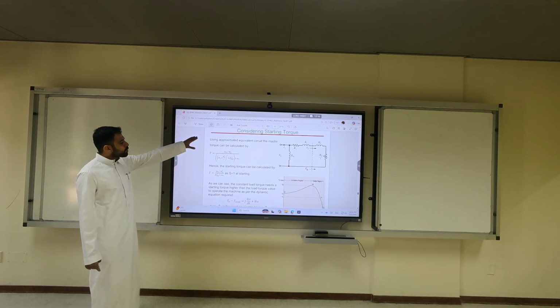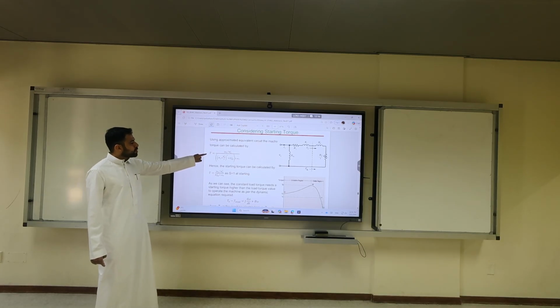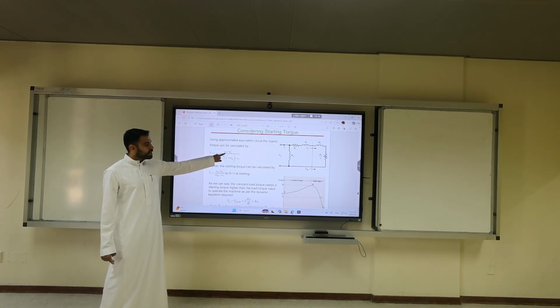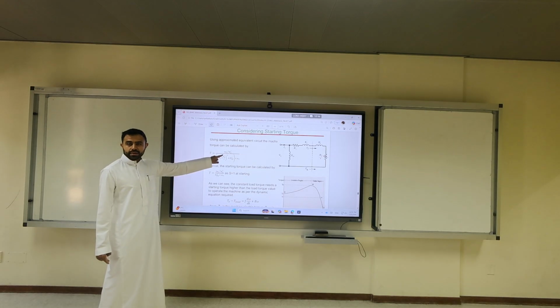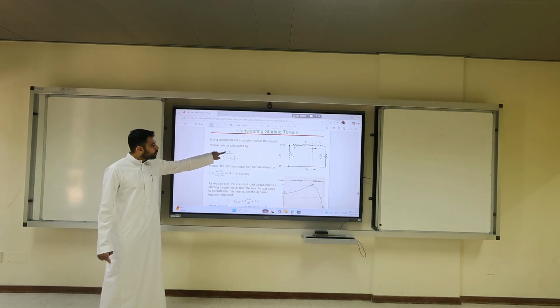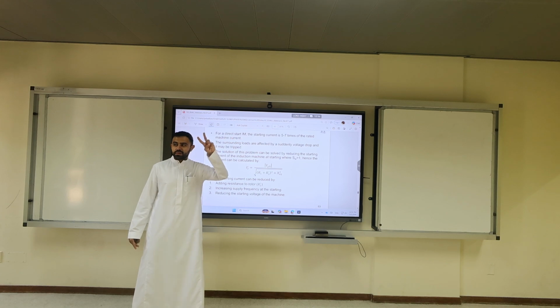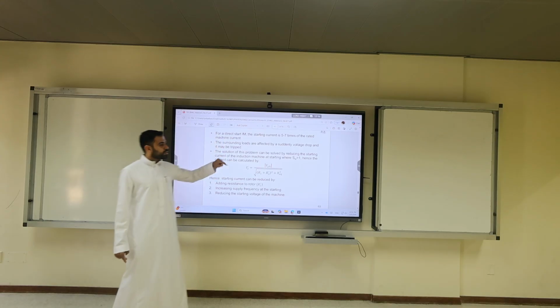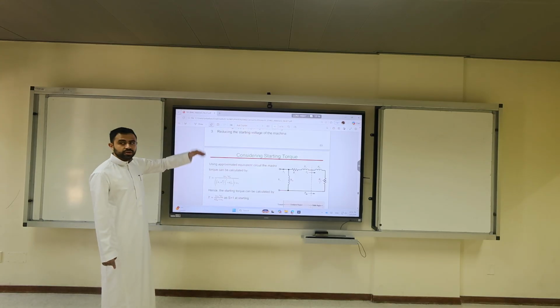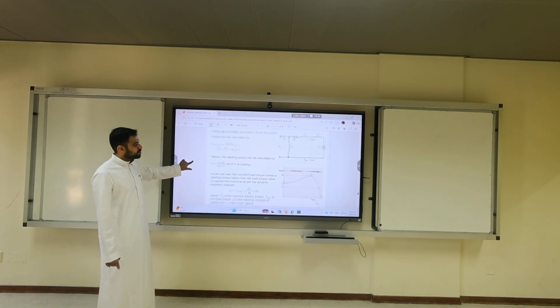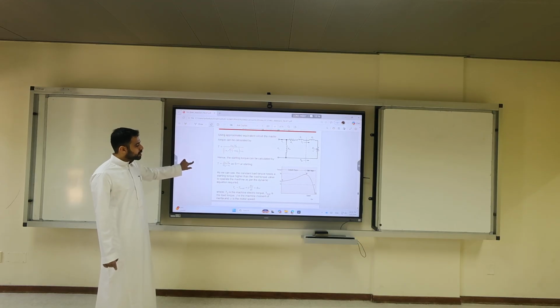So if we use the approximated circuit, we can estimate the torque to be 3V1 squared. V1 here, is it phase or line? Phase. So we use V1 or the symbol V phase. You have two symbols for V phase. And if it is pure V, what does it mean? Line to line. Okay? You need to get used to different notations. You are seniors.